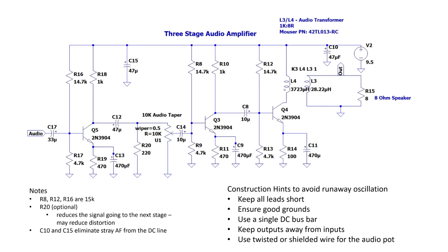The side that has a higher DC resistance, say around 50 or 60 ohms, will be the primary, and the one that has a lower one, maybe around 1 ohm, will be the secondary, which goes to the speaker. Now, those are DC resistances. Those are not the AC impedances that you would expect. So we still want an 8 ohm speaker at the output.